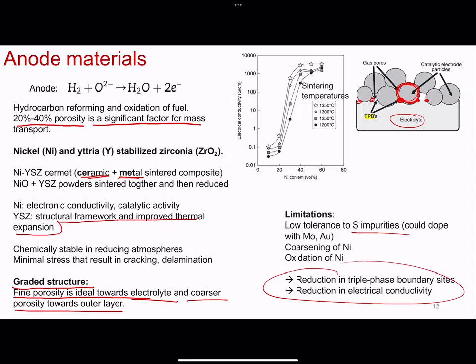So if you operate out of that temperature regime, you won't have the high ionic conductivity phase. If you have all these mixtures, right, your compound has this cocktail of stoichiometries, what tends to happen is you'll start to have decomposition, where you may stabilize the binary phase, where you have this complex ternary ceramic compound, or you have quaternary, or you have quinary.